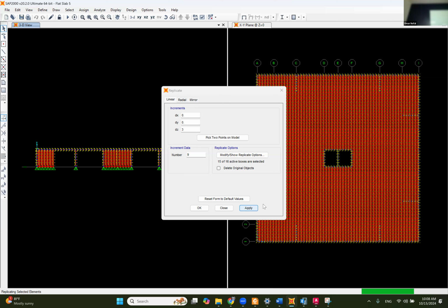And if we have isolated footings, usually we put hinges. But if we have raft foundation or pile foundation, we will put fixation. So it depends on how the situation is happening down here. Is this restraining everything, the bending moments and the forces and everything? Then I can put fix in here. Okay, so it depends on the foundation type, and it depends also on the soil, if it's providing fixation to the column or just restraining the movement. Okay. All right.